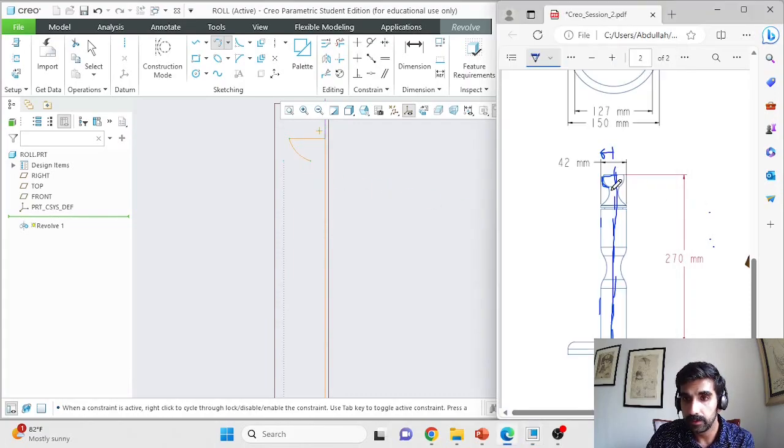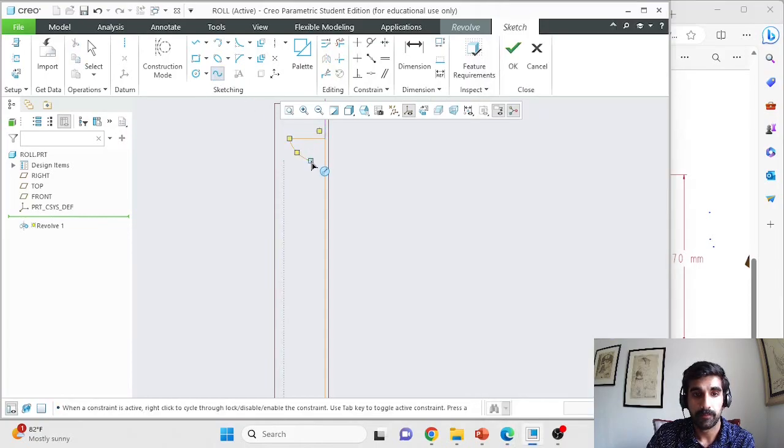The next thing that you need to make is this curved feature, and this is not a circular arc, so it's not a circular arc exactly. So what you will use is not the arc sketching tool, but the spline sketching tool, which is this over here. And with spline, similar to line command, you select multiple points, and that helps you create curved features. Select a point over here, select a second point somewhere over here, and then when you start selecting the third point, depending on where you select the third point, you will be able to create a curved feature.